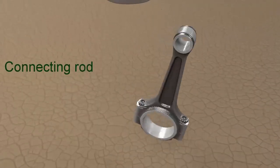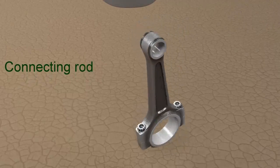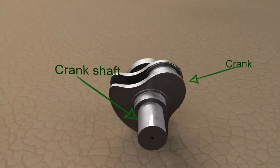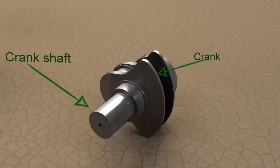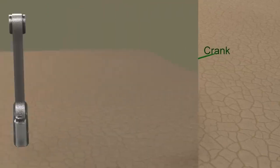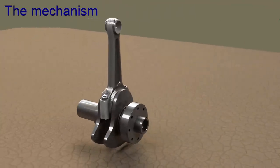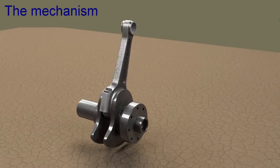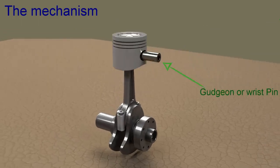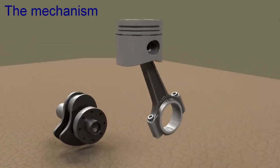Connecting rod interconnects the piston and crankshaft and transmits the forces from the piston to crankshaft. Crankshaft converts the reciprocating motion of piston into useful rotary motion of the output shaft. The big end of the connecting rod connects to the crank and can freely rotate on the crank. The smaller end of connecting rod is connected to piston using gudgeon pin and connecting rod can swivel around the gudgeon pin.